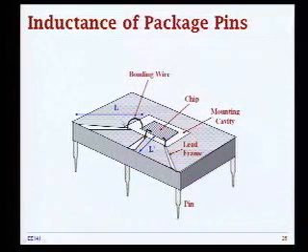This is the standard scenario where you have second level routing. If you assume that the first level routing is the on-chip routing, then in the second level routing you connect the pads from your chip using bonding wires over to these package interconnects. And then you have these package pins that are further connected into a printed circuit board, where you have your PCB routes.